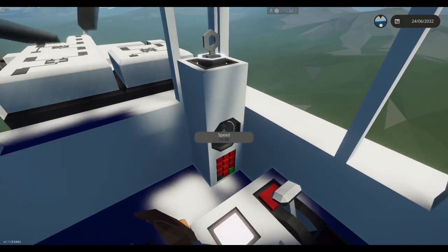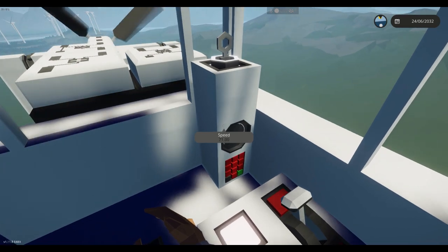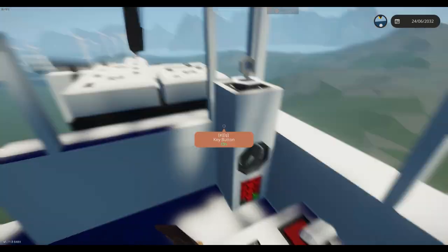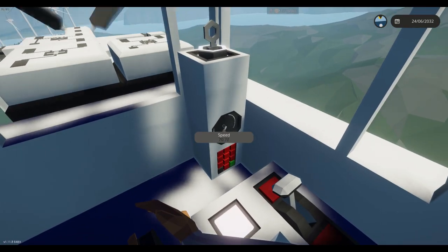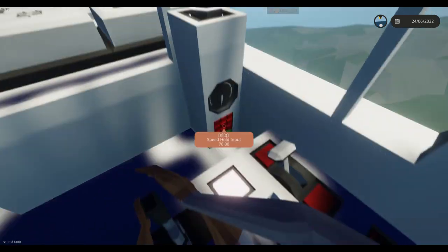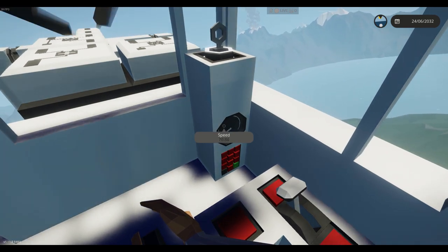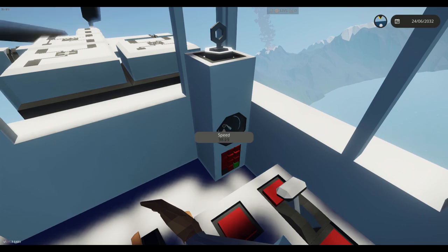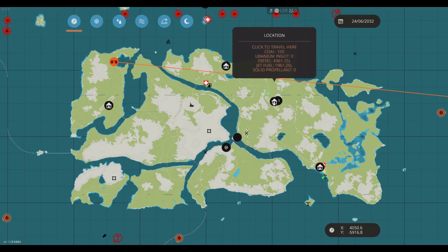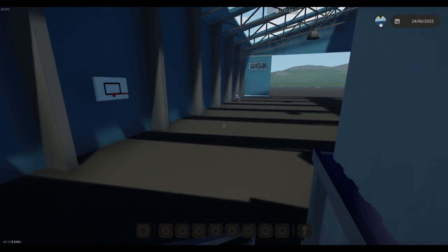It's changing a lot because we're also changing altitude. But this is closer to what I want, and in my book, this is good enough for my standard. This is now complete. We have our speed hold system working. If I want to, I can take it off, and I can use the up and down keys to control my throttle. So you now have a system where you can control manually, and you have an automatic system. We are going to now move on to the next stage in building.